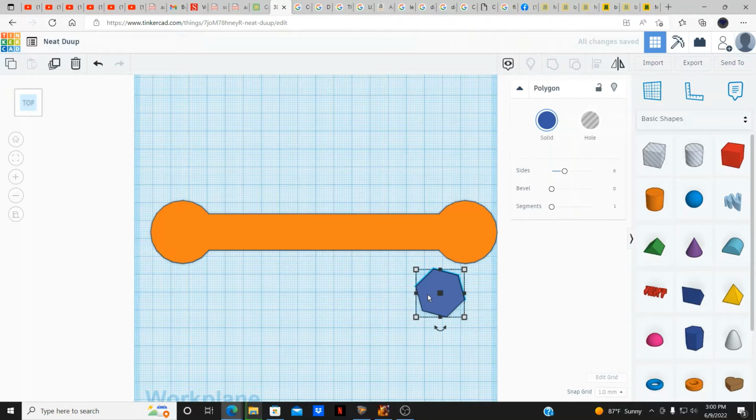Click the shape. Drag it onto here as far as you can. I'm going to bring a line around here-ish. Let's bring it down just a little bit more. I'm just doing it by hand. I'm just eyeballing it. You can do the same thing on your side. There we go. Voila. Okay, now our next one is going to be adding our hole feature.